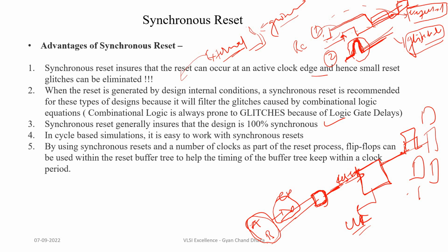The further advantage is in cycle-based simulation, when everything is evaluated based on clock cycles, it is easy to work with synchronous reset because we can update each and everything based on clock cycles. So always in cycle-based simulation, it is easy to work with synchronous resets.